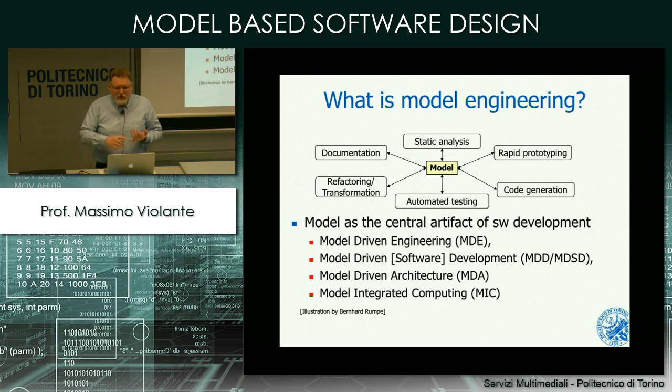We don't care about the color of the vehicle. In first order of approximation, we don't care about the shape. What is relevant is the mass of the vehicle. It is relevant to know the type of shock absorber that we are using, okay? Which is the characteristic of the dampers that we will control in order to implement the active suspension system.